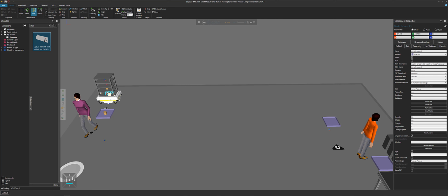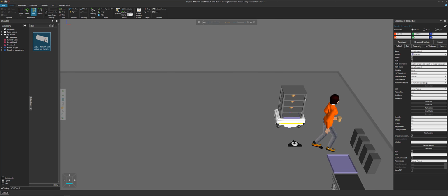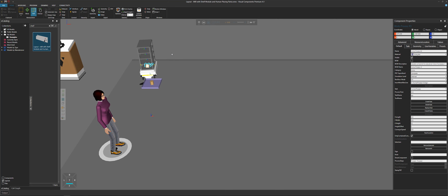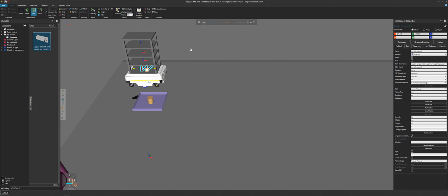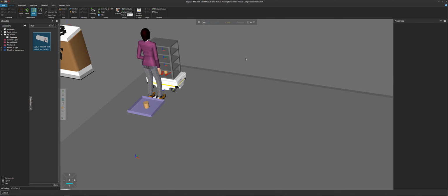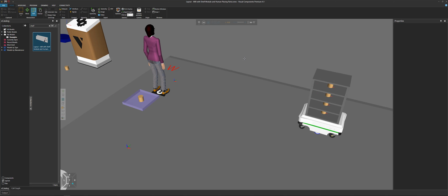Remember, that delay at this station will only happen when the robot gets back here after finishing its delivery. So once it gets the 4 parts, boom, it'll take off. The delay here is happening after we unload each part. So let's start counting. So around 10 seconds. Go back over here. And now we'll wait 10 seconds before the human worker can start loading it up again. So same approach as before in other layouts, just a little bit different of how we need to set up the pattern and loading and unloading the parts to the robot.